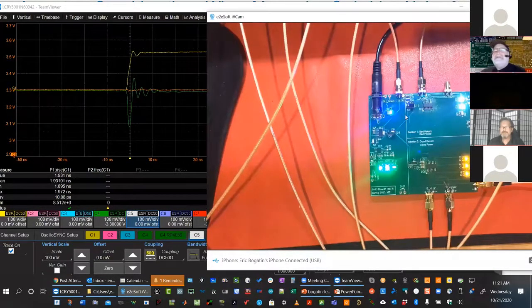If you had just gone ahead and said, I'm going to measure the voltage noise on my rail, that's going to tell me how much switching noise I'm going to see. And if you went and measured, you'd say, wow, that's great, I have no switching noise. But that's not telling you what's going on on the die, because it's those decoupling capacitors that are filtering that switching noise on the die from getting on the rest of the rail.